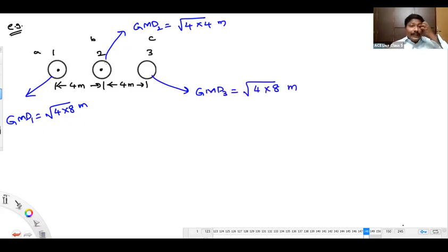Observe now, this middle conductor has the lowest GMD compared to the outer conductors. So this middle conductor will experience more corona compared to the outer conductors in this case. Yes or no?